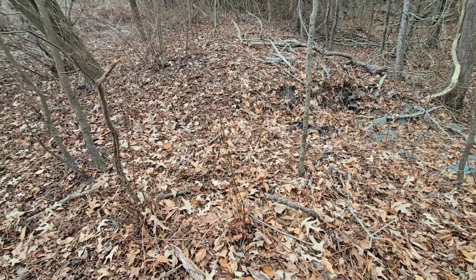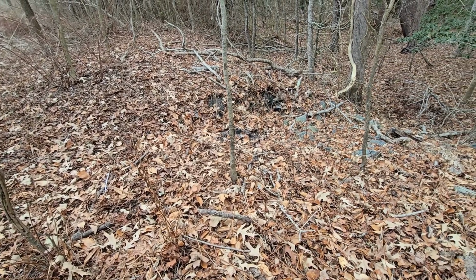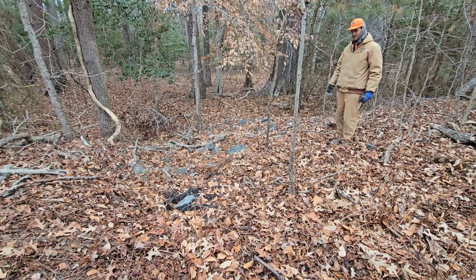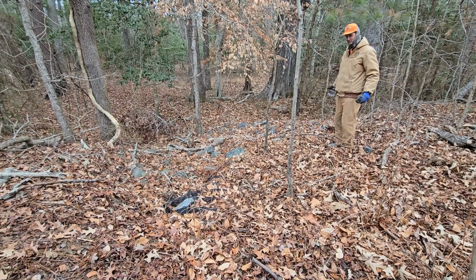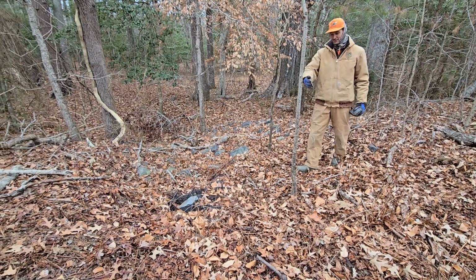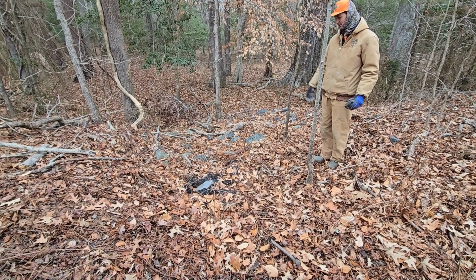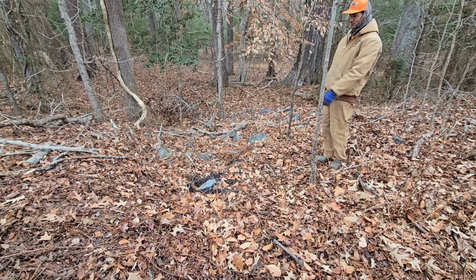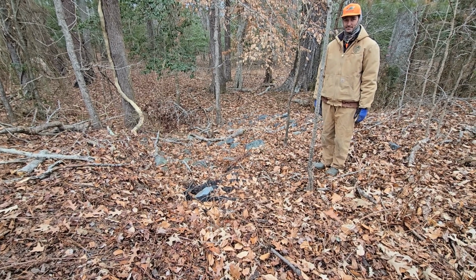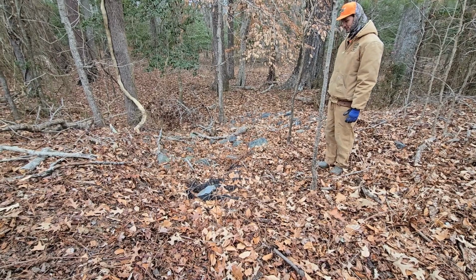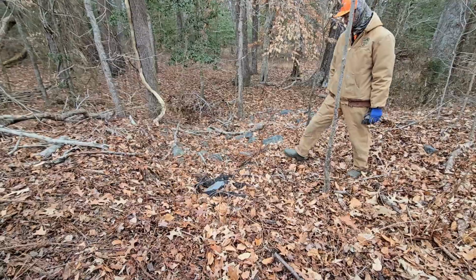We observed that the spillway needed maintenance because water flowing over the spillway was washing out a section of the dam. So it seems like they built the spillway 20 feet wide expecting water to sheet flow over this entire area, but in reality, the low spot in the spillway is right here, and we're only seeing water come through this left edge, and they didn't armor that side nearly as much. You see any signs of erosion? There's certainly signs of erosion and head cutting. You would point it out to us.